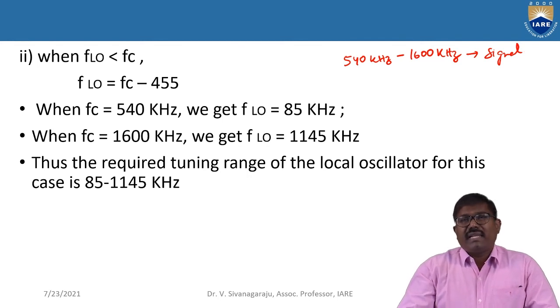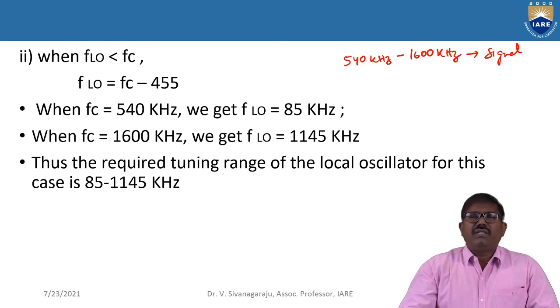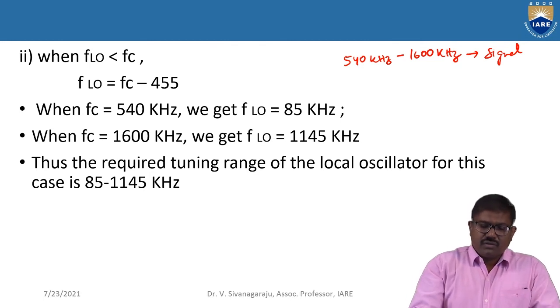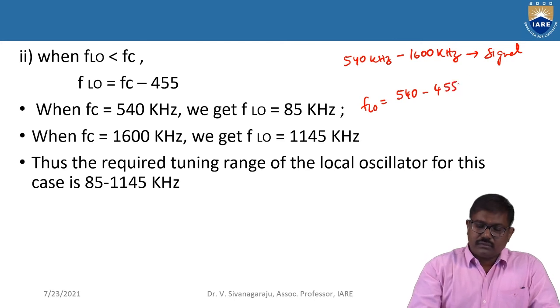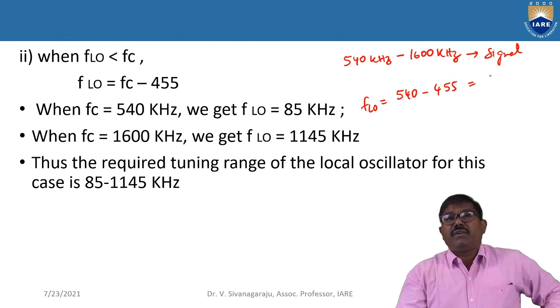Now when FC is 540 kilohertz, what is the local oscillator frequency? We know the formula, FLO is equal to FC, here 540 kilohertz, minus 455 kilohertz.